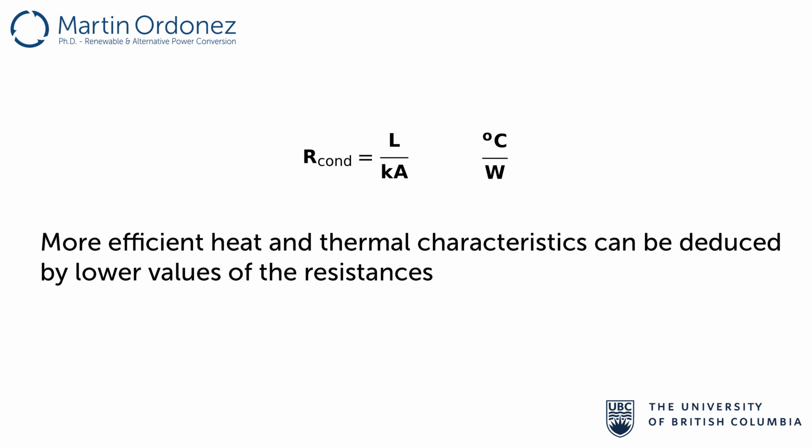Therefore, knowing the heat source value, which is the losses of the circuit, and the thermal resistance values, we can analyze and manage the temperature of a specific component or a circuit. It should be noted that this thermal resistance should be calculated for each component or part in your circuit. This means that for each connection in your circuit, you have to calculate a thermal resistance.